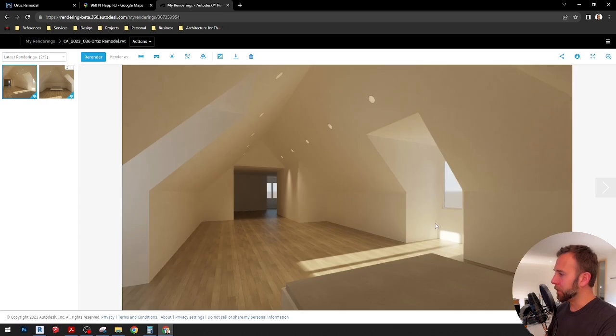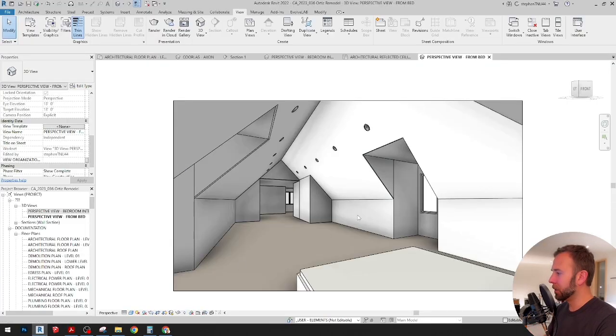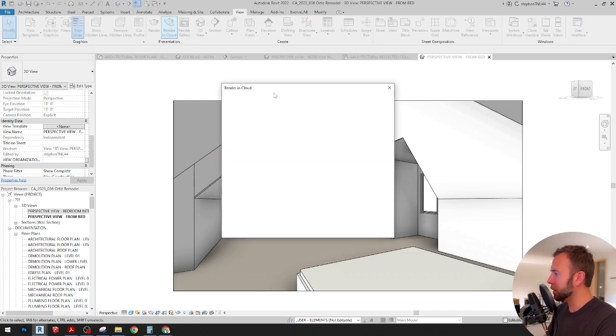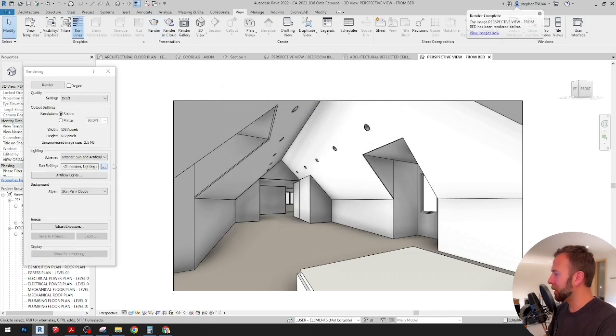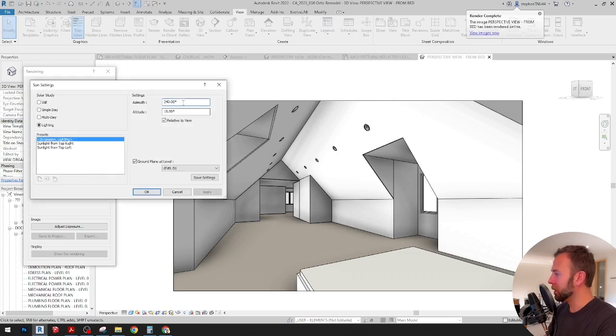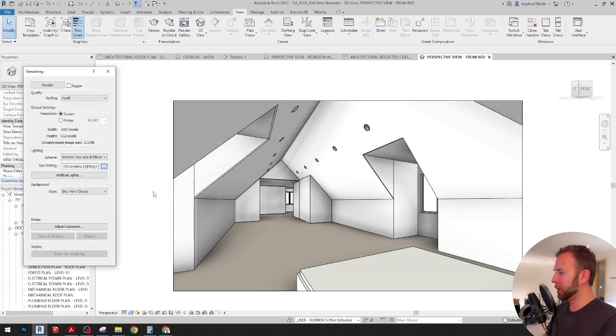Not intentional. But I think pulling it back towards us so we see the face of this dormer that we can see illuminated is a good thing. So I'm going to adjust the sun angle to be closer to the camera angle, so maybe another 20 degrees. Drop it down to 220. Apply. And that looks even better, just illuminating the whole space.